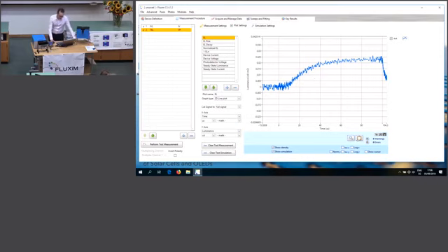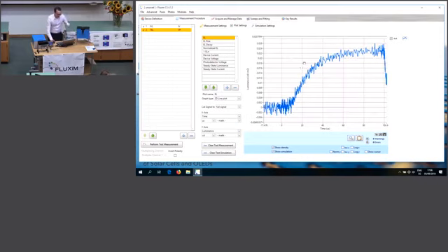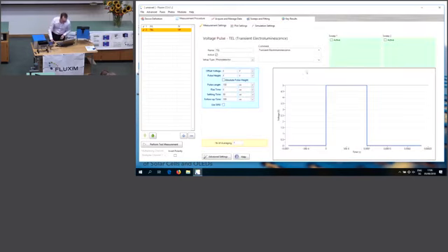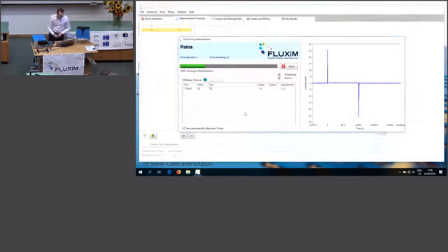Before, I mentioned that you can vary lots of parameters, what we call sweeping. I can do that now, for example, by varying the voltage from 5 to 6 volt, and let's say we make 4 steps. You can see here a preview of what we are going to do. We press start, and it does all these measurements.